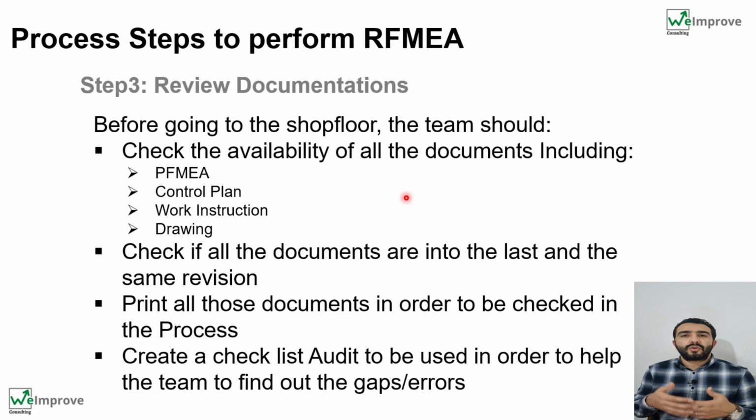The checklist is not required, but it will help anyone go deep into details to find the potential failure modes. Because if we give anyone the documentation, PFMEA and so on, and ask them to go to the shop floor and check if there is any potential failure mode, they will just look at the document, the shop floor, the process, the machines, and maybe they will not find anything. But if you give them some structured questions, maybe they will go clearly to the point to find out the risks.